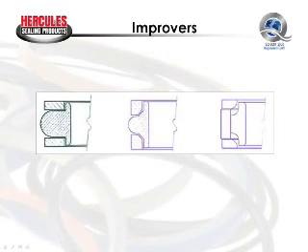And our third example is a further evolution of the T-seal. Here we have what's called a four-piece piston seal or a capped piston seal. And here we have a T-shaped sealing element with two backup rings, which is the same design as taken from the wide base, but then the seal designer has put a Teflon sealing element on top of the T-shaped expander ring. Now you'll notice that this sealing element is square. It's actually rectangular, but would be referred to as a square lip, which gives better sealing performance in a contaminated environment.